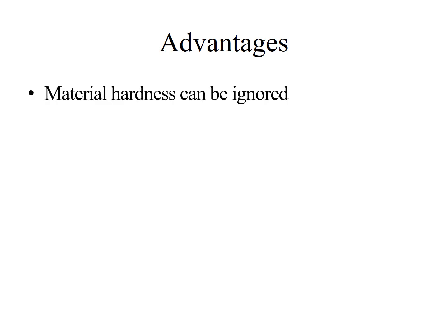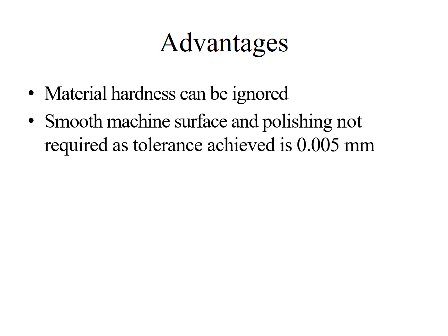Advantages of electrical discharge machining include that the material hardness can be ignored. Any type of material can be machined using this. The hardness doesn't matter. Then the machined surface is smooth and polishing is not required as the tolerance achieved is 0.005 mm.